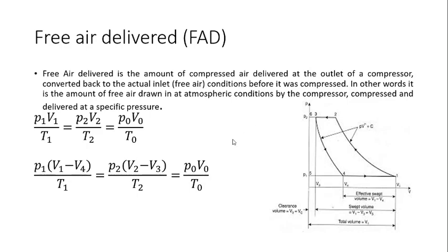So in order to compare the performance of the compressor, we need a standard. That standard is free air delivered, and the volumetric efficiency in terms of free air delivered. This is the standard for comparing the reciprocating compressor.